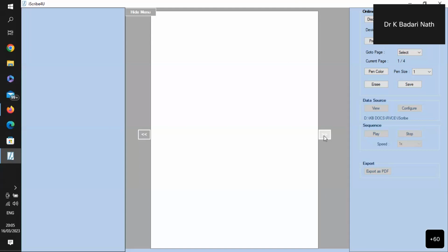Now, the stack requirement is very much there. If somebody asks in the low level language, machine level language, why is the stack required? Number one, whenever we call subroutines or nested subroutines, the stack is a place where I can store the return addresses.